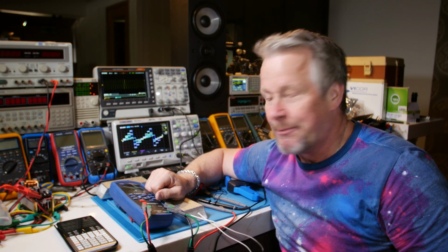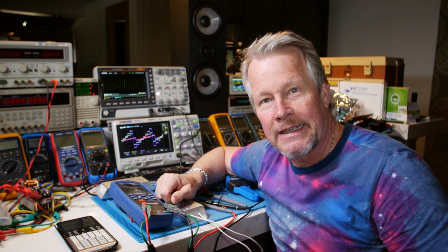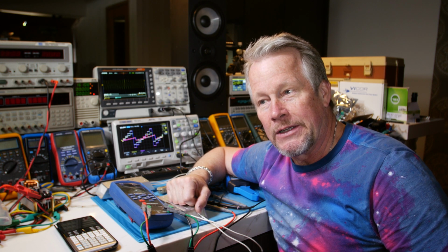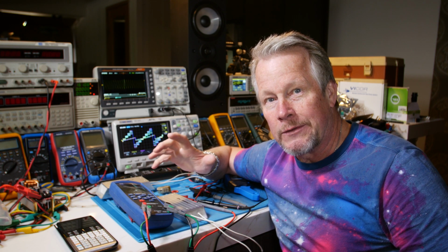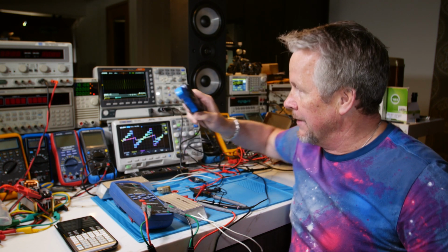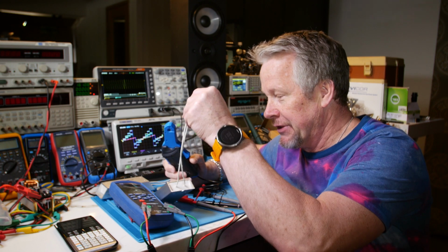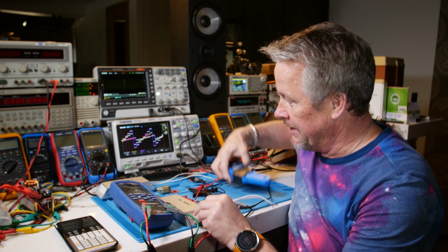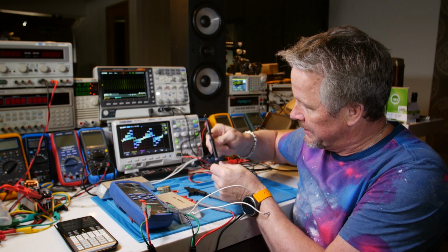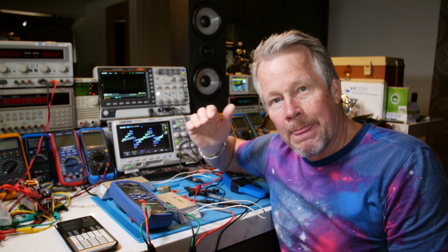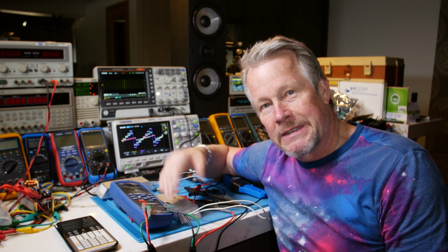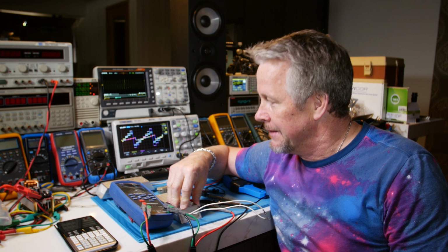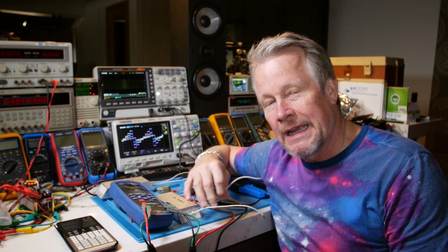So hey, I'm going to use this GW Instek, which has a really cool way of doing it automatically, and now manually you can do it as well. Let me explain how it's done. You dial up a frequency, you inject that frequency voltage into your resistor, you measure the current, and with the voltage probe, you measure the voltage. You take the voltage, let the scope do it for you, take the voltage divided by the current, and you get ohms, impedance, right? So now resistor has no phase angle.